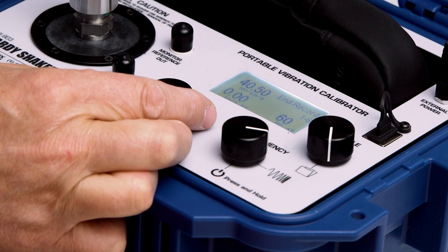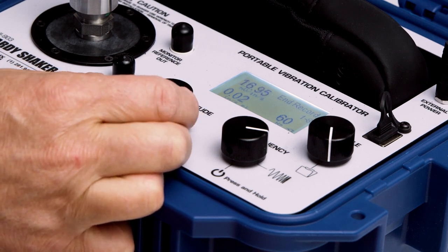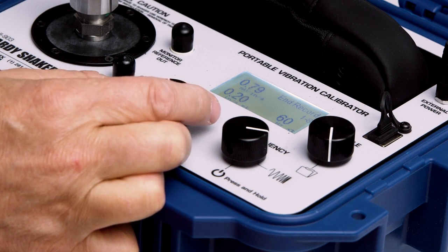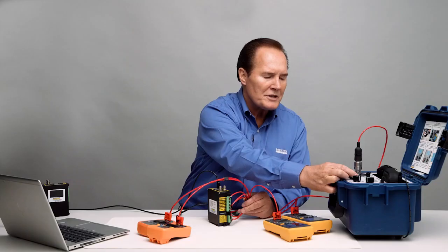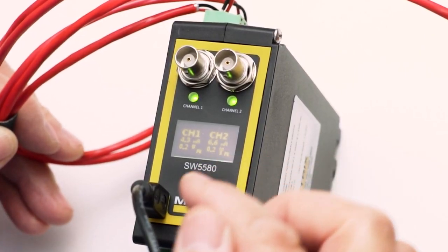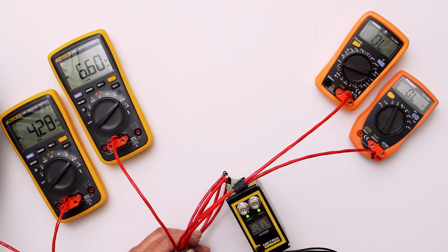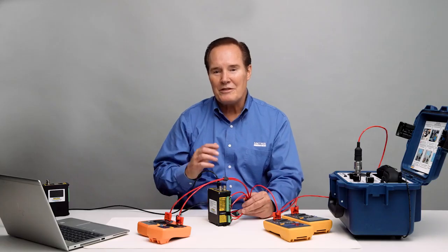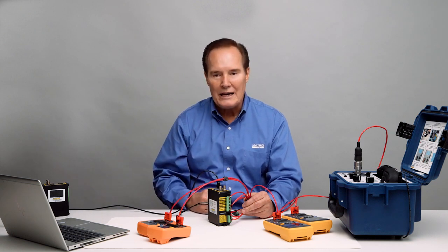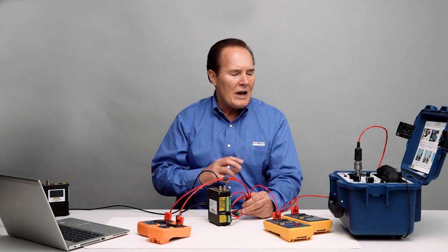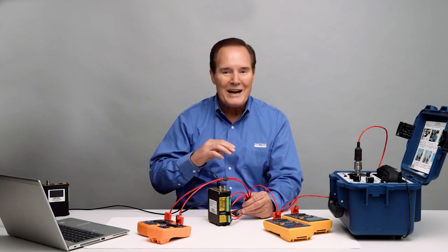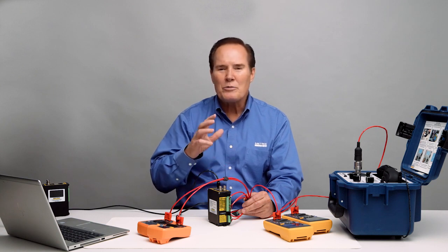We'll just go ahead and increase to 0.2, a little overshot just a little bit. And here we have 0.2 inches per second at 60 hertz. And we should see the same thing on our screen, which we do. And we see close to 7.2 milliamps. It has to be within 5%, which it is. 5% is 0.8 milliamps, and it's well within 0.8. So let's go ahead and increase it to 0.4. When we increase it to 0.4, we're going to go past 0.25. Let's go to 0.3.